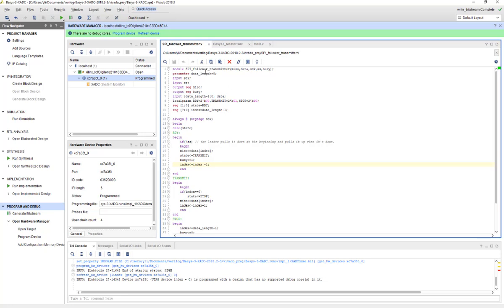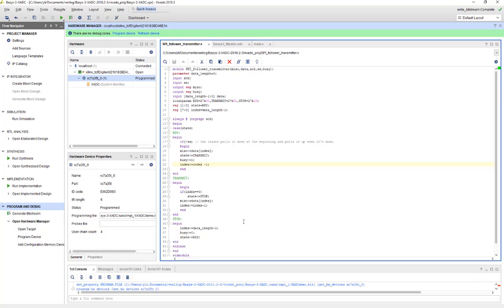And for the SPI module, you can see that there is a busy line here, right? So what's happening is whenever it pulls down the enable pin, it starts taking every single bit from the byte data input to MISO. So MISO is just one single output port. It's a serial line, so it's taking one by one using the index. It starts from the MSB and decrements that index by 1 each time.